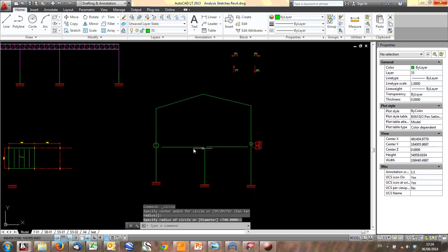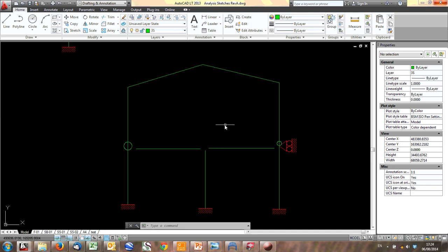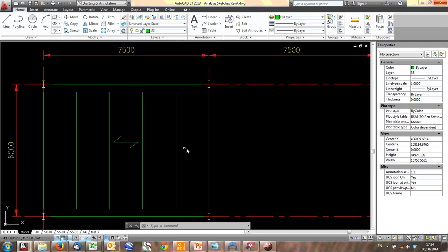Once again, you prop it there and you can stabilize it. Or if you have to, you make it moment, and you can really carry the loads more efficiently if you know where it's going, if you know where floor bracing, roof bracing, etc. Let's say now there's no concrete slab on this thing. Let's say the floors look like that and there's just some grating on top. How do you do that?